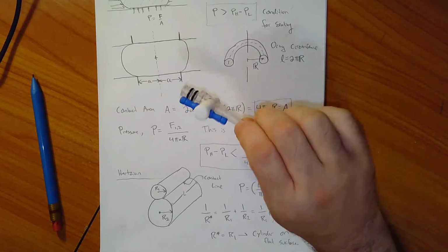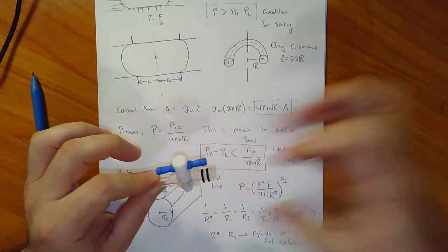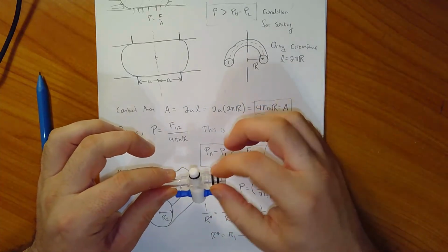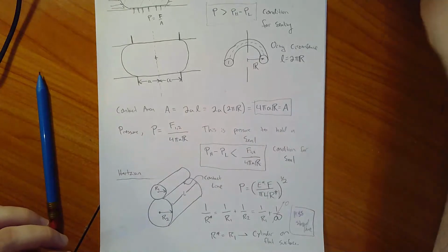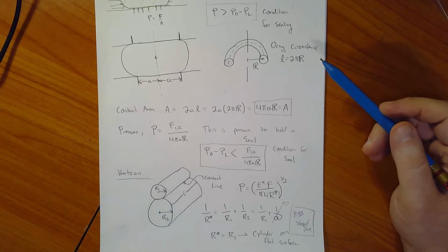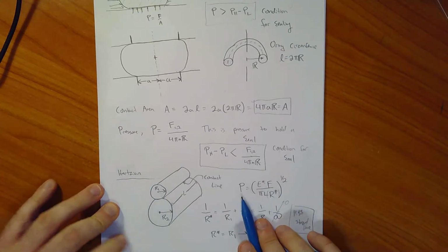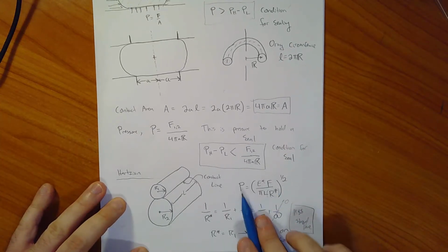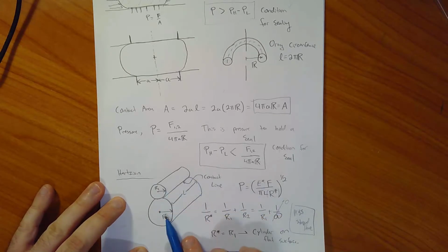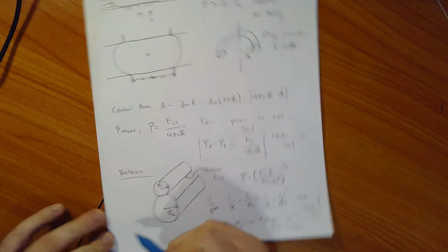Of course, we're doing the analysis on an O-ring on our stopcock here, which sits inside a Buret, which fits over, and these O-rings seal. Okay, and the point where I got to when I stopped the last lecture was effectively here, and we had written the Hertz contact equation for the pressure in this contact space between a small cylinder and a big cylinder, and I had explained what R star was, which basically, if I blow this R2 up and make it effectively infinitely big, right?